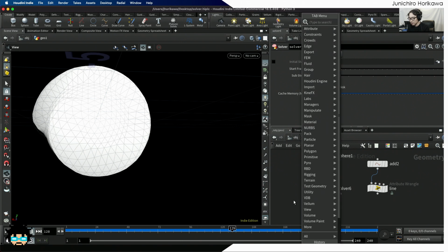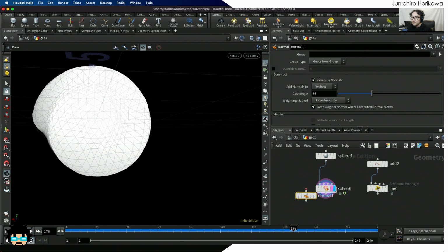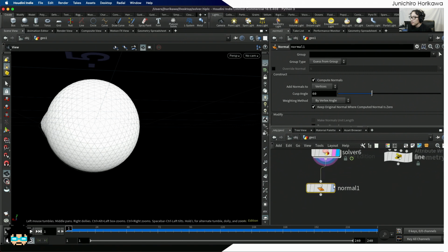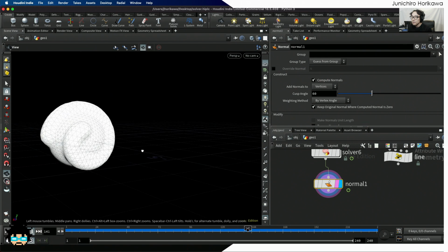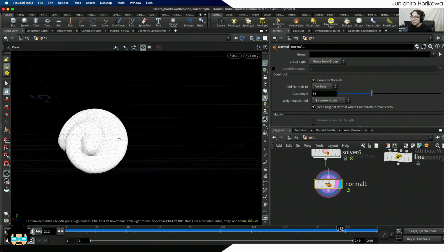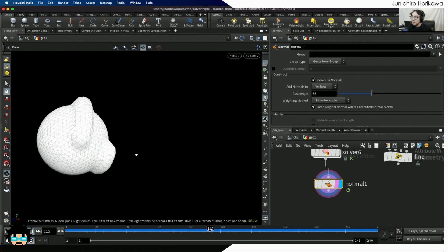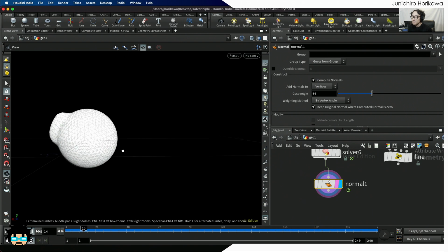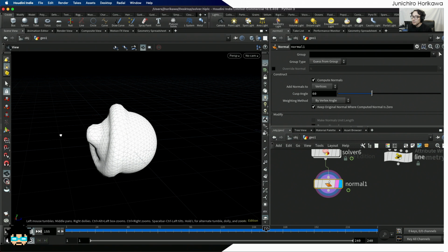I might also need to attach the normal, to make the normals cleaned up right after you have modified the point height of this geometry. So you can create this kind of animated geometrical modification using the SOP Solver. Not just moving the points, but modifying the geometry would work as well.